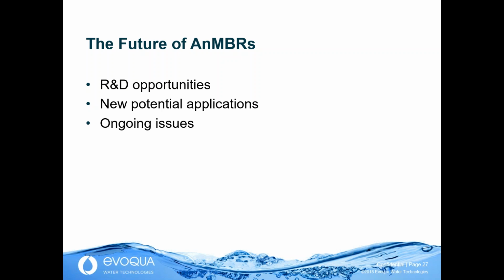I don't know if it's necessarily a one-off, because they do pair well together. If you have a high-strength wastewater, you remove all the organics from it, and all you're left with is a low concentration wastewater. It does make sense to just polish that wastewater off, get the DO up, get the nitrogen out, and then discharge it. The application I talked about at Kellogg's was kind of a perfect application, because the COD coming in was fairly high, and we had strict discharge limits since we were going direct to a nearby creek. So the two together worked very well in that instance, and that might be something that we see more going forward too.